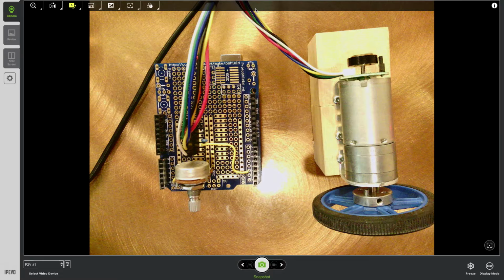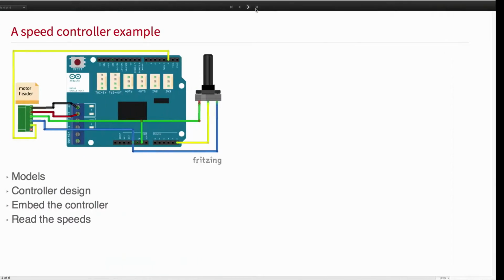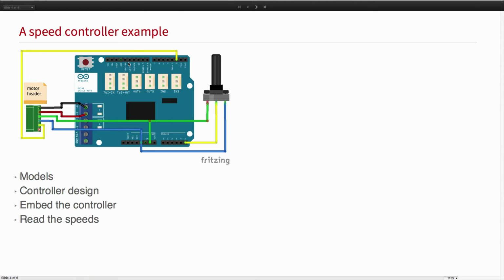And then the Arduino is going to compare these two values and compute an appropriate signal to send. It's going to send it on pin 11, because the motor shield pairs pin 11 to channel B, to which I've connected the two leads of the motor.